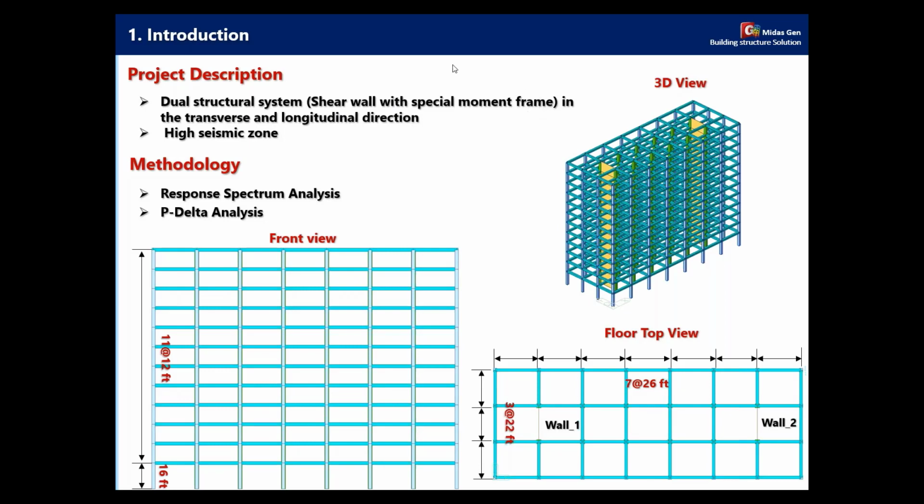Special moment frames are really good in designing reinforced concrete members, because it's really economical when you use this type of system in your design. For the seismic zone, we are going to use a high seismic zone when we analyze. The methodology we are going to use in the design is the response spectrum analysis and P delta analysis.